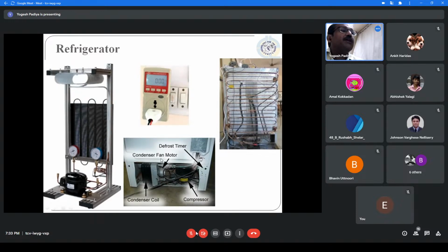Second, the condenser coil can be of this type, which is in quite old ACs if you have an old fridge. But nowadays you are finding that the fridge backside is totally closed. There, the condenser coil is placed somewhere here. It is a compact coil. Now through this coil, air is passed. It means that this coil's surface area has been shrunk down and made compact. Now, obviously, if this fridge is again kept close to the wall, the air is not coming and not going, so less air circulation occurs.